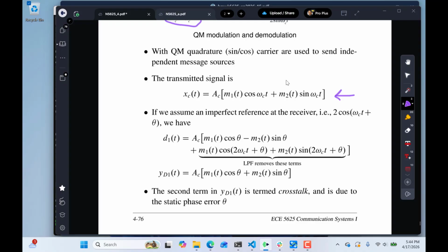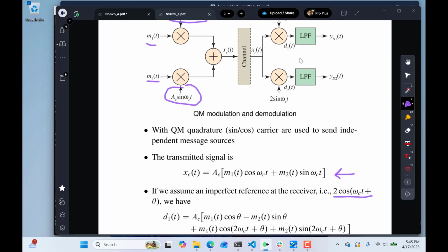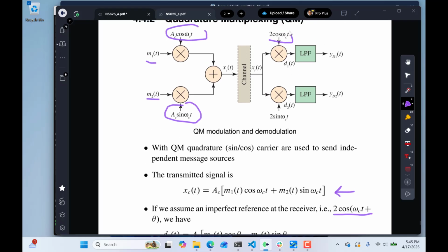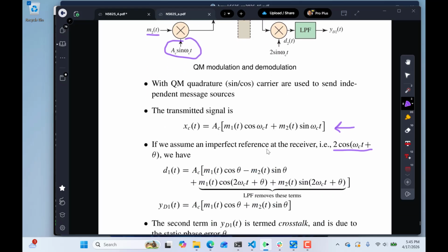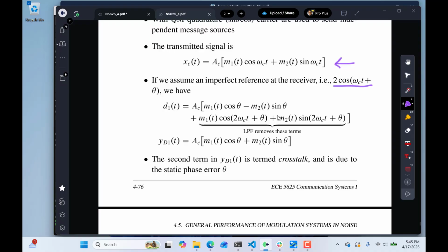And then I can do the same thing for the second signal, but here I just multiplied, just looking at how I did this. I'm not remembering for sure how I did this. I multiplied by 2 cosine, and then I get these 4 terms coming out. So the cosine is sitting right up here, but it's multiplying times the composite received signal, which has got both terms present in it. So I've done all the multiplying things out, and you can see you get double frequencies on both the M1 and M2, but those will get removed by the low-pass filter.